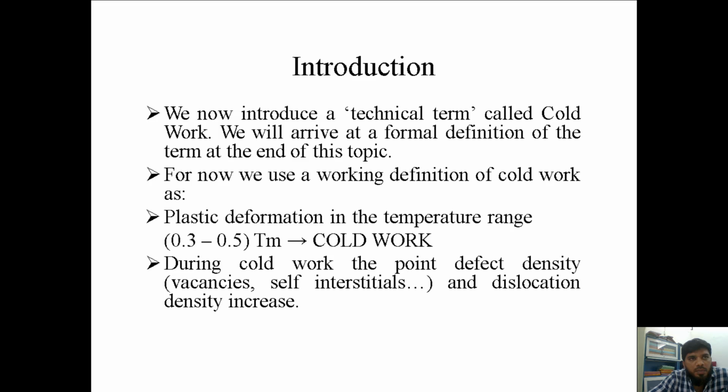During cold working, the point defect densities will be increased. When you are continuously doing cold working, the point defect densities keep increasing, and because of the point defects, the dislocations will be increased, which further makes the material stronger, but the material will become brittle. Why does it become brittle? Even though the strength of the material has increased, as it has a large number of dislocations, once the material starts breaking, it has already gone through plastic deformation, so further it will not deform. Once you apply the stress, it will break easily.